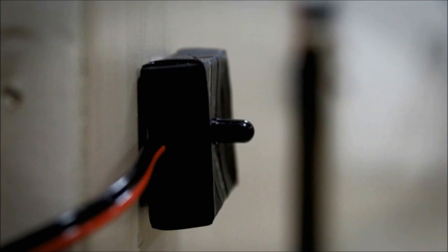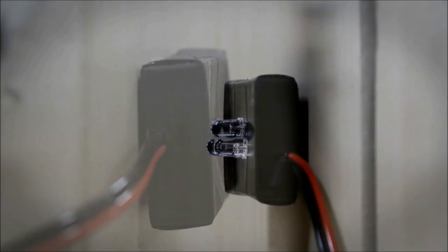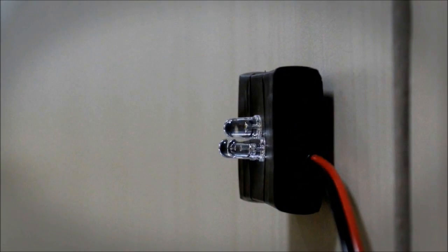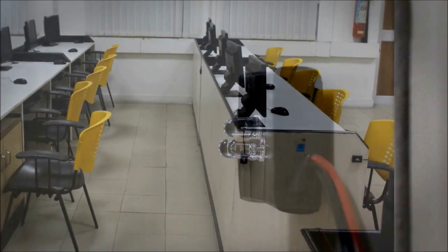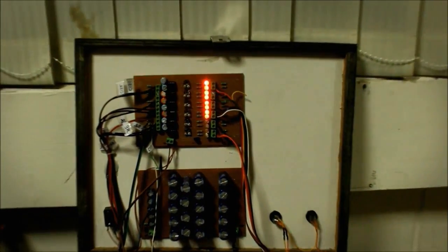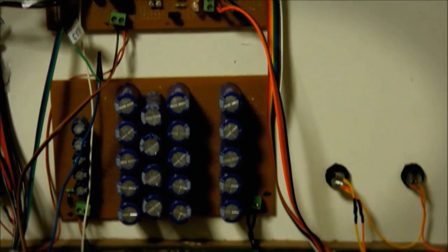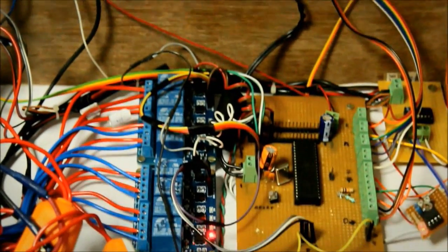The proposed system was implemented in the software laboratory of EDC Research Lab under the School of Electrical Engineering. The IR sensors were installed in the rows, and in places where they could not be installed, the USB connections from the CPUs were used. The control box was placed near the AC switch terminals and the relays were connected in parallel to the manual switches such that the existing system remained undisturbed.